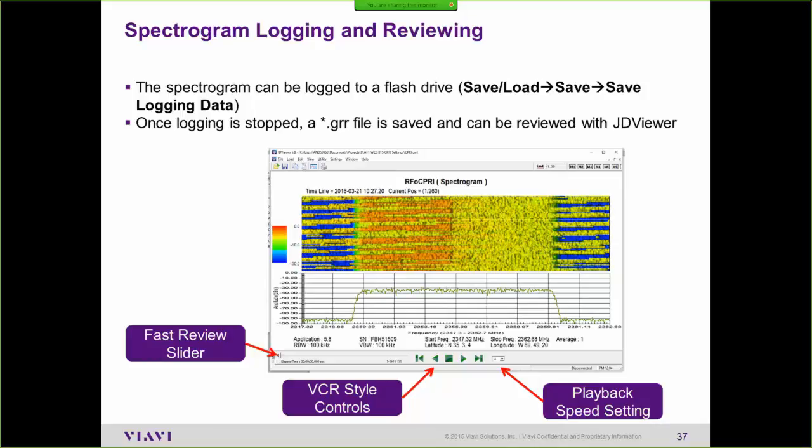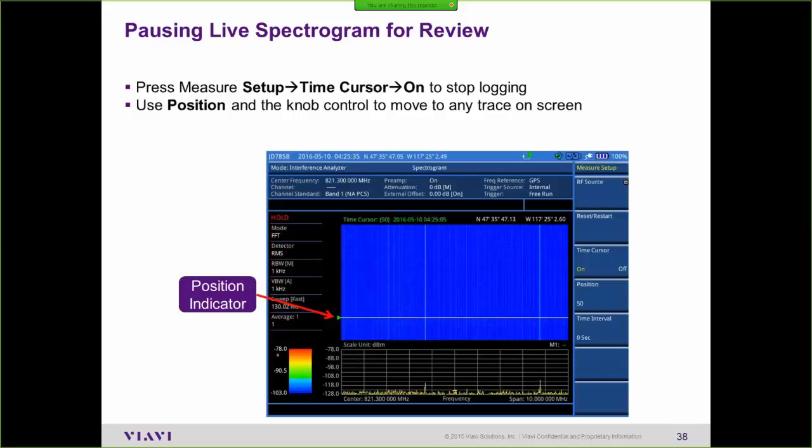So let's talk briefly about interference hunting. I have 5 rules that I try to live by when I interference hunt. First one is I want to see what the receiver sees. If I can't see what the receiver sees, or I can't see interference on the receiver, it's not interference. Because you can go out in a sector and find interference all day long, but if it never gets back to your receiver, it doesn't matter.